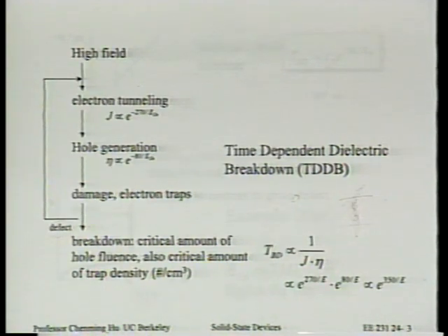But machines also carry electrostatic charge. So there can be a very short electrostatic discharge pulse, just like the spark that jumps between your finger and the doorknob of a hotel room after you walk down a long carpeted hall on a dry day. That's called electrostatic discharge. But this will cause a breakdown. And that pulse can be as short as the tens of picosecond range.